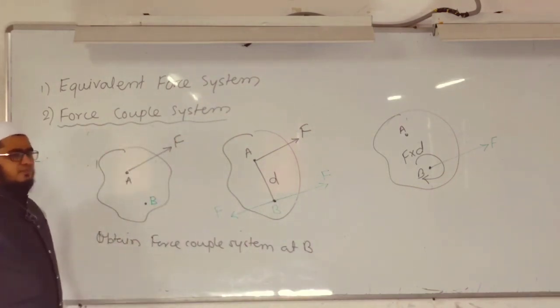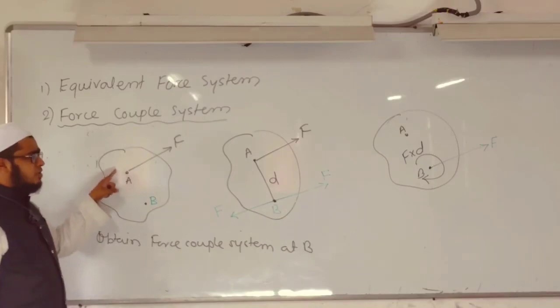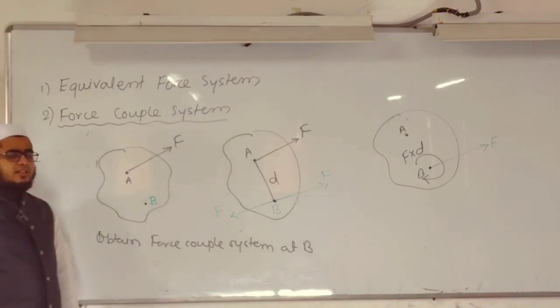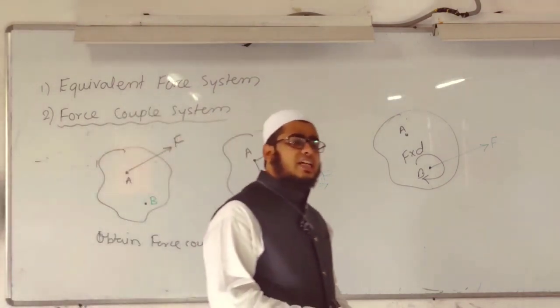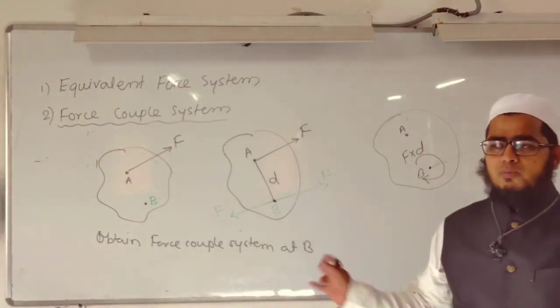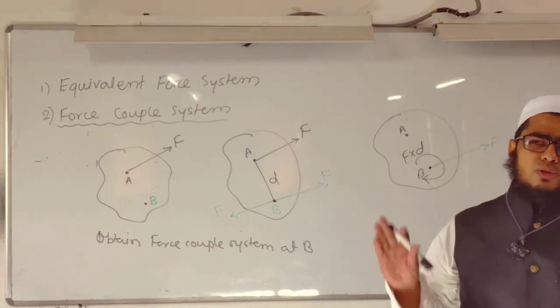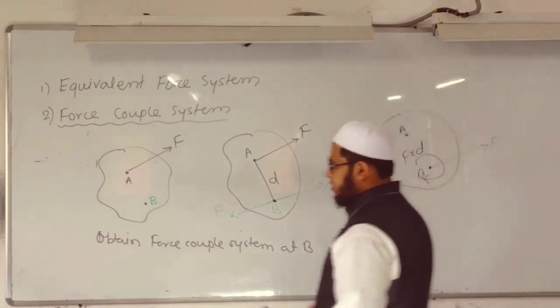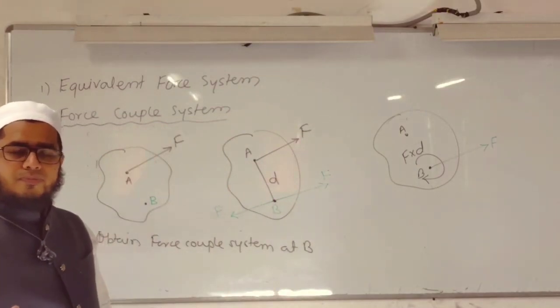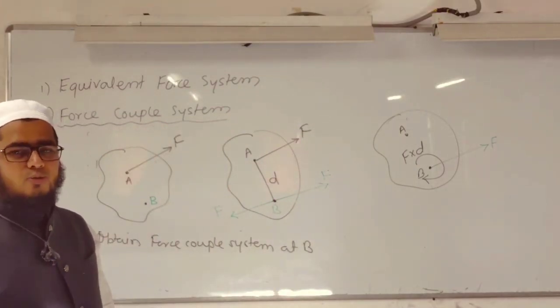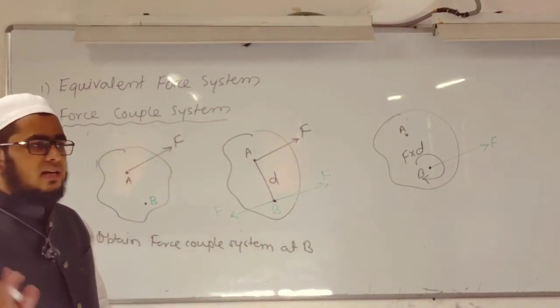Whenever the force couple system is required at a particular desired point, transfer the given single force. I will explain the steps to obtain the force couple system. Transfer the given single force to the desired point with the same magnitude and direction.